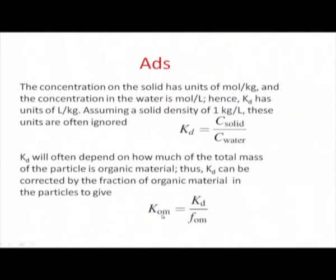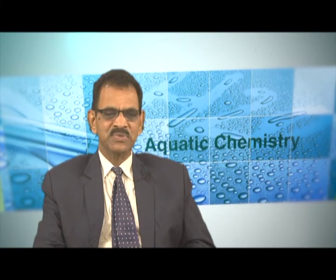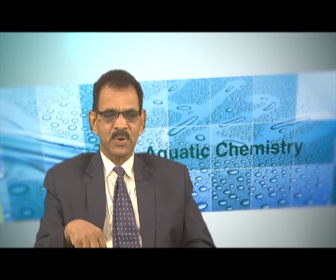Suppose you know the fraction of organic matter value; then with the Kd value divided by the fraction of organic matter, we can express the partitioning coefficient value in the organic matter without doing any experiment, simply by this correlation. So, this process is similar to the partitioning coefficient of solid to liquid or into the protoplasm in the aquatic system; this is another thing which can also be explained based on adsorption behavior.